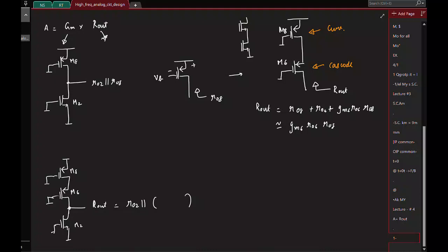By the small resistance R02, right? So this is not buying you anything. So what should you do? If I had a PMOS cascode, the output resistance increases a lot. But if I just put it here directly, it's not helping because finally it's getting dominated by this guy.